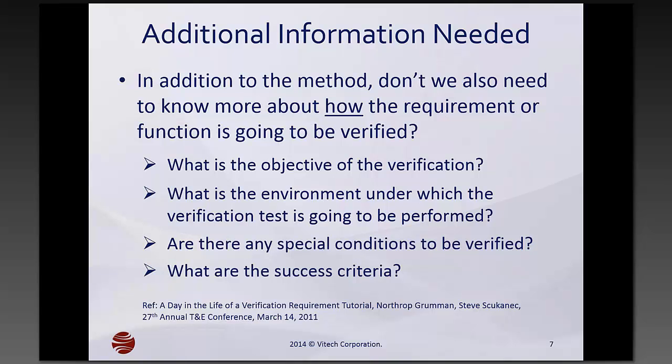within the system pressure, and we're going to test it at 800, at 1,000, and at 1,200 pounds, and if they had said something like, we're going to test them at these 3 set points, maybe 2 or 3 times at those set points, and the success criteria was 8 out of 10 times that they had to close within a certain time frame, they would have got much more information in test and would have avoided those problems in the operational side of when they went out to operational testing.